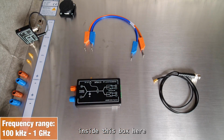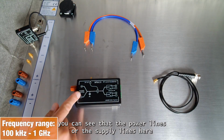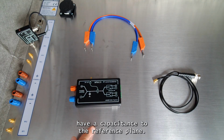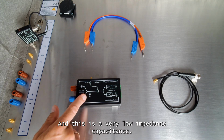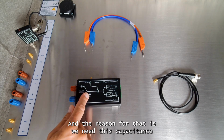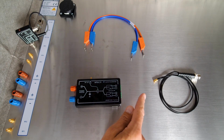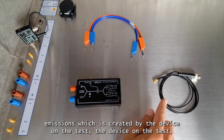Inside this box you can see that the power lines or the supply lines here have a capacitance to the reference plane. This is a very low impedance capacitance, and the reason for that is we need this capacitance here for all of the disturbance of the emissions which is created by the device under test.